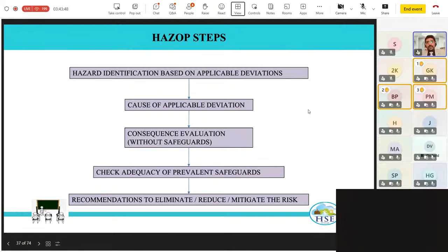Now, when you have an overfilling of a tank scenario, you could have an overflow from the tank that could lead to local spillage, which could lead to a slip trip hazard or a combustible mixture formation. So that would be the first consequence. And then the second consequence could be that if the overflow is not adequately sized, then the least resistance could be from the vent flow path, and that could go on to a KOD and then to a flare, which could lead to a fireball and a fire rain in your flare.